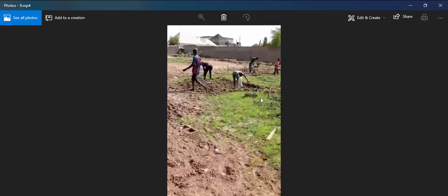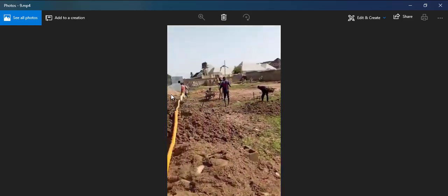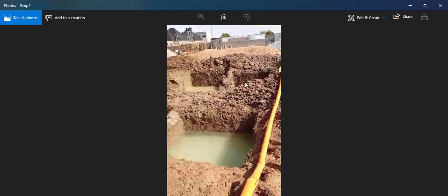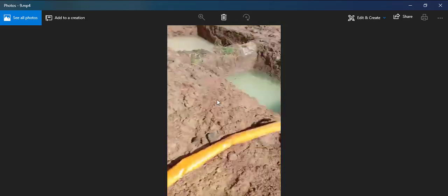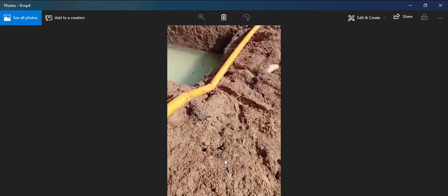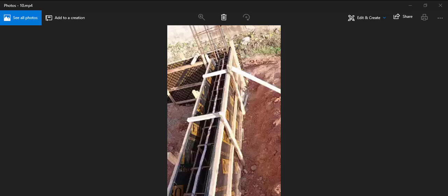Very important. So for that type of area, for an area that is waterlogged, I wouldn't advise you to use blocks to do the foundation and to raise the foundation up. I'll prefer you do a retaining wall, or you do a ground beam, instead of using the blocks. Whatever height you are going, either you do a beam, reinforce the beam running around, or you do a retaining wall, depending on which of them.